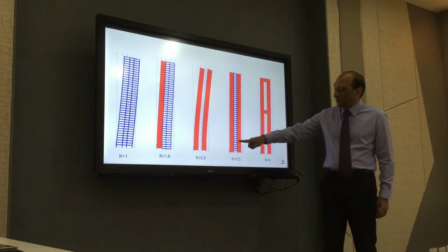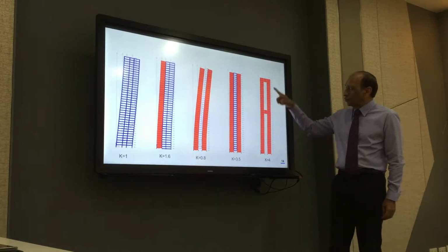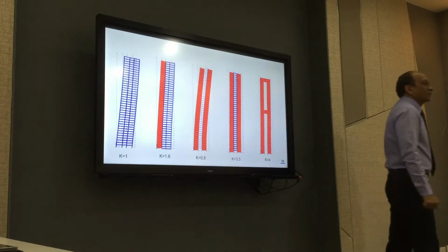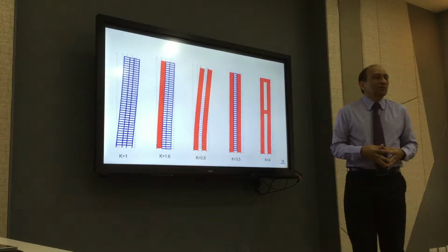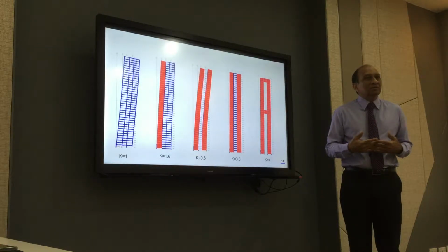And I add a wall with connecting beams, a little bit big, and I add a wall with 2 very big connections. You can see the increase in stiffness. And you will also see a change in the axial forces in the wall with each addition. So this is one example where you can improve or adapt the system by changing how the systems connect to each other.